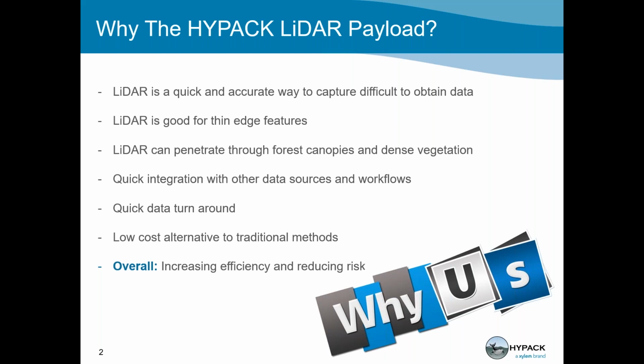And as hydrographers or surveyors, we usually have all of the necessary sensors you need to operate a LiDAR survey. We all have GPSs, computers, are familiar with wiring things, and that's all you need to run a LiDAR survey. So it integrates really well with our other workflows and our existing toolkits. LiDAR also has very little processing, as we'll show you later today. So it has a really quick data turnaround compared to some more computationally heavy methods like photogrammetry or the tedious aspects of cleaning data from sonars.